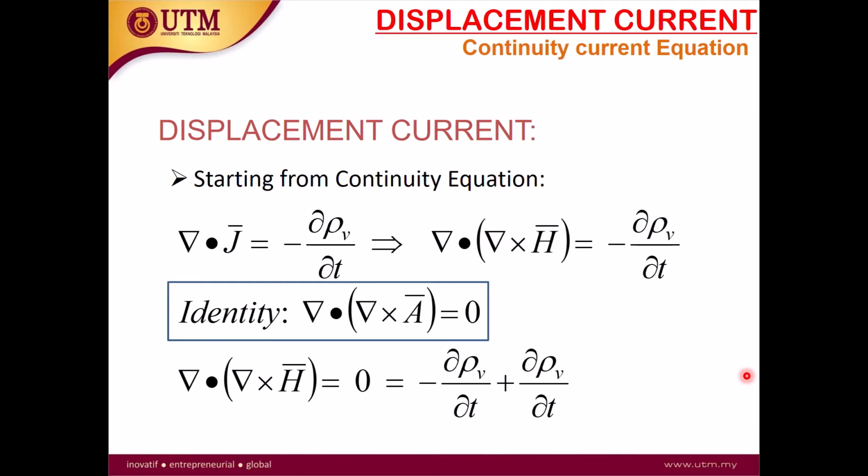When we supply the DC current to the capacitor, what happens? Because the capacitor is designed using two parallel metal plates separated by a dielectric material. Dielectric means it prevents the flow of charge. That means there will be no current flow. So when we supply the DC current, the capacitor seems to be an open circuit.